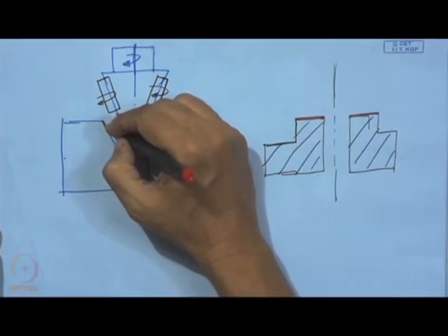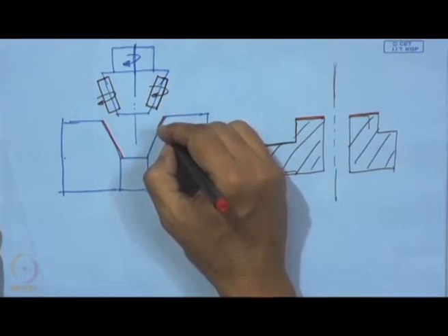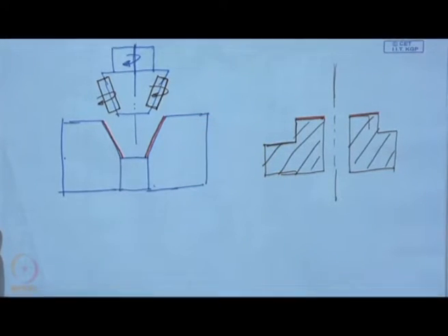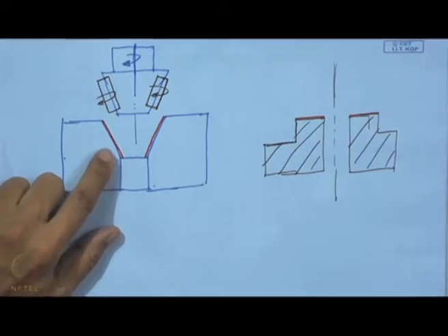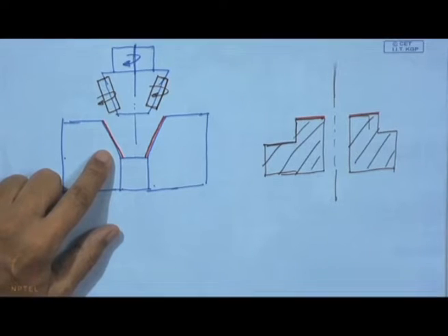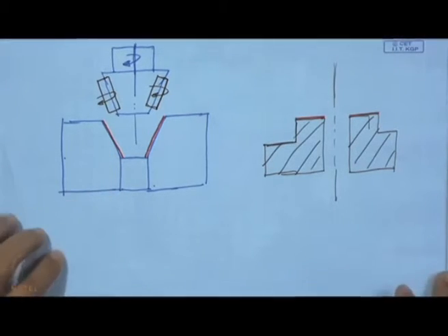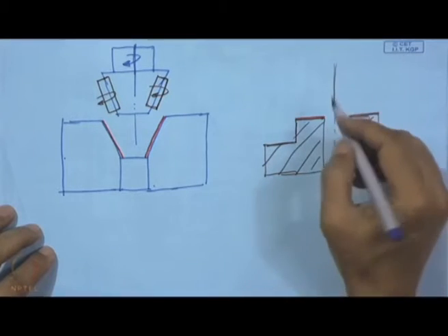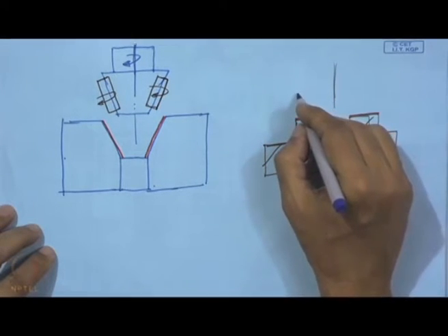What we have seen here is the surface of interest where we need some mechanical surface modification. That means we have to deform this surface to change the stress situation, to improve hardness by work hardening, to remove all those machining marks, and to improve oxidation resistance, corrosion resistance, all those things. Similarly here we can do this rather conveniently using one such roller.